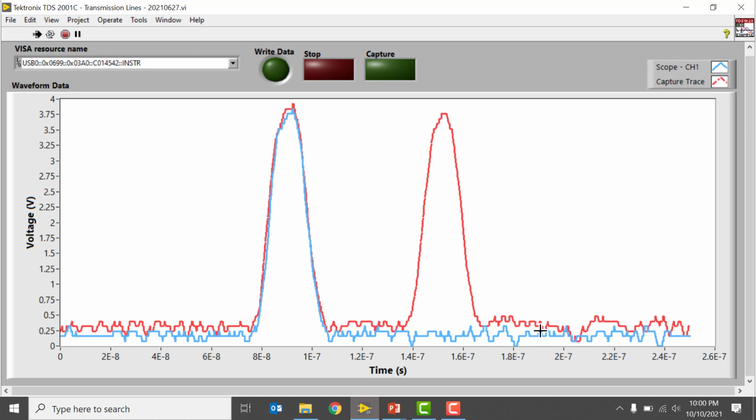If you think back to some of the other results from our analysis of transmission lines, we had the reflection coefficient, which was determined by the load impedance minus the characteristic impedance of the transmission line. So it would have been ZL minus Z0 divided by ZL plus Z0. And so if you think of that for the case of an open circuit, the load impedance is basically infinity. And so the ZL in the numerator and denominator would both dominate Z0, and you'd expect the ratio of those quantities to be +1, so a reflection of +1.